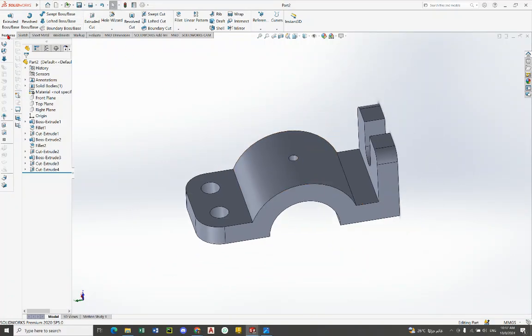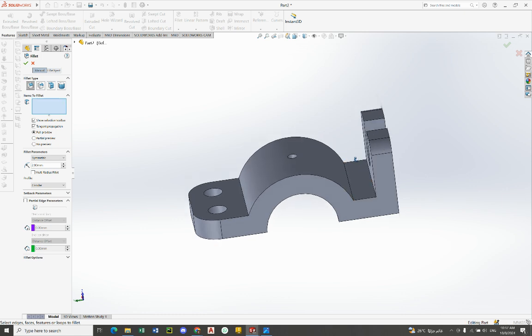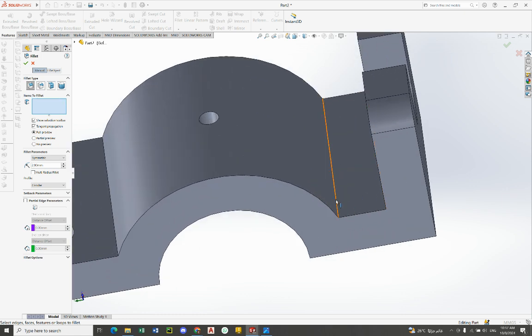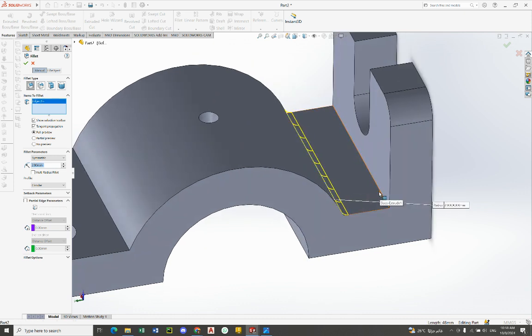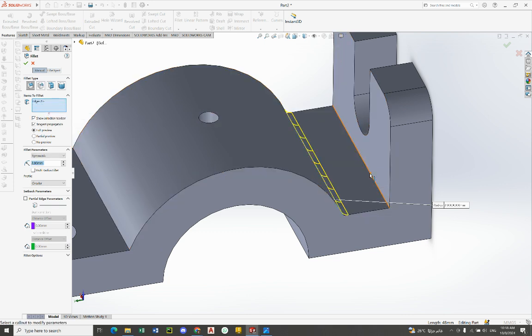Small fillets of radius 2. We enter Feature, Fillet. I choose the fillet radius 2 as mentioned in the document, and the fillet of the edge here. Now I choose all the corners to fillet. The first corner is here. I click on this edge, on this line. Click also on this edge. Not on this one. If I want to delete it, I right click, delete. Just click on the orange line in order to catch the edge.